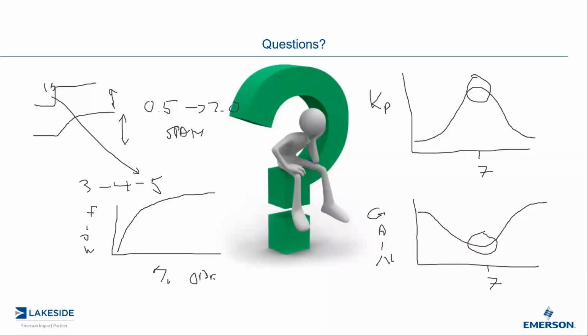You get the idea. Right around 50% here, most of my flow change occurs before 50% and very little afterwards. If you have a butterfly control valve that's operating at 65, 70%, you're not controlling. You're barely modulating at all.